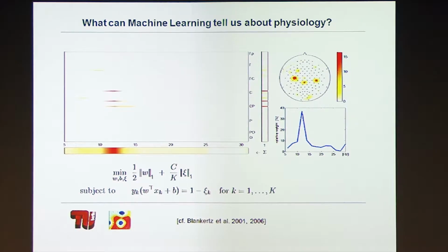And then we can look at what the program tells us about what is important in this tensor, okay? And that's what this matrix is about. So here's frequency, okay? If we average everything along all channels, then we get that the salient signal is somewhere between 10 and 13 hertz, which is the alpha rhythm, or the mu rhythm in the case of motor imagery.